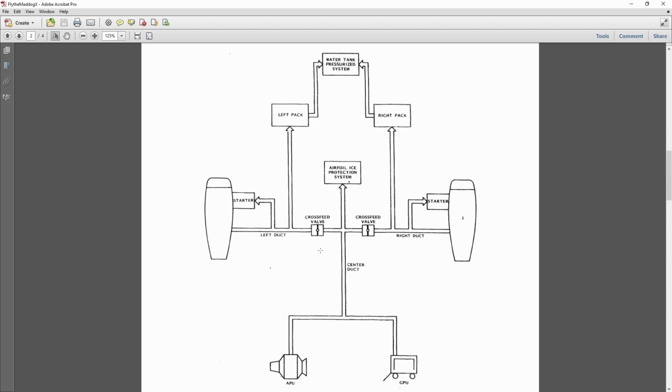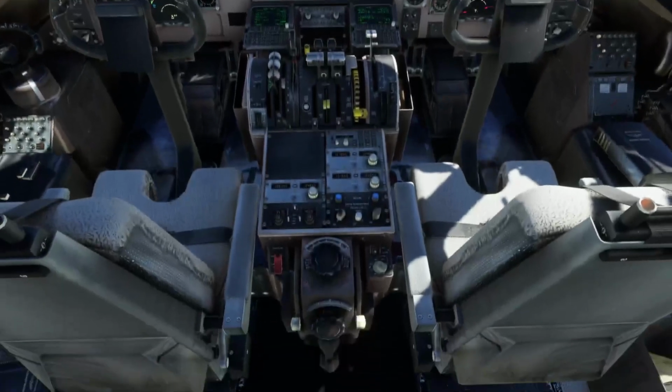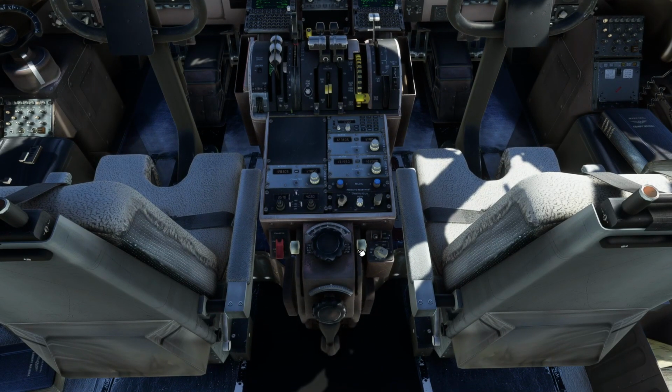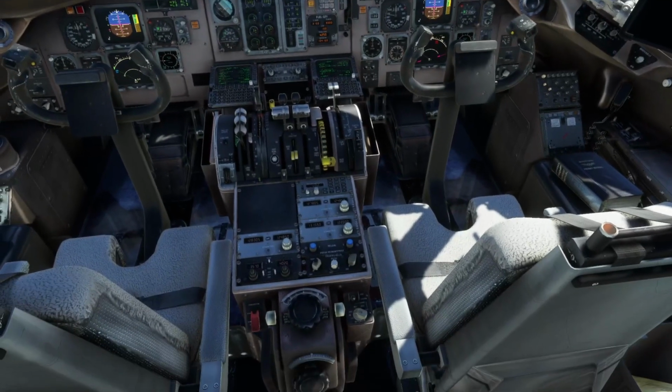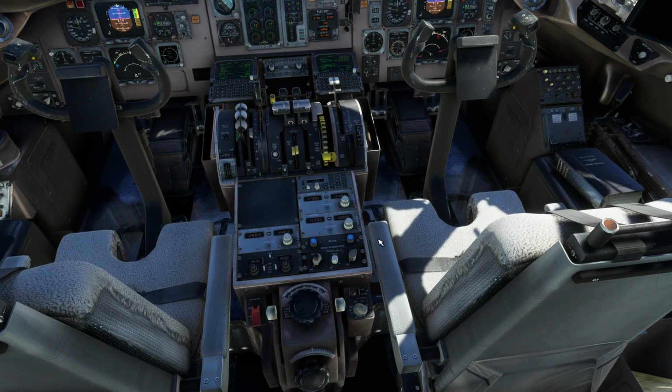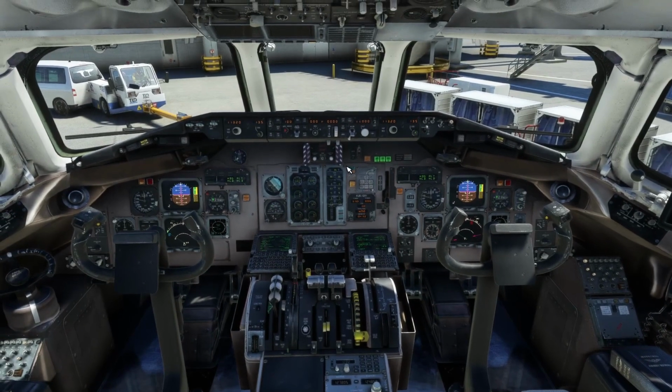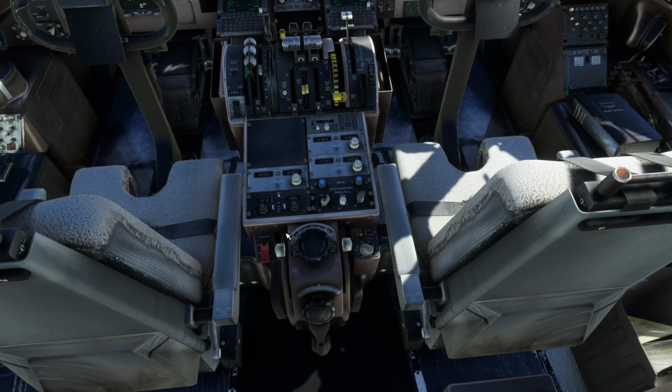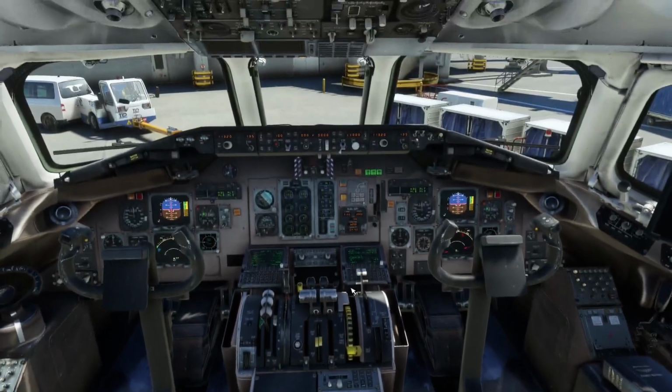And it's very easy to miss because they're behind you in the aircraft, and they're right here. They're these valves right here. That is open. That is closed. Open. Closed. So first thing I do, I come in here and I open those valves up. And usually when I shut the airplane down, I open them up too, mainly because I'm usually running air off the APU. But it's also nice to leave those in the up position for the next crew coming in.